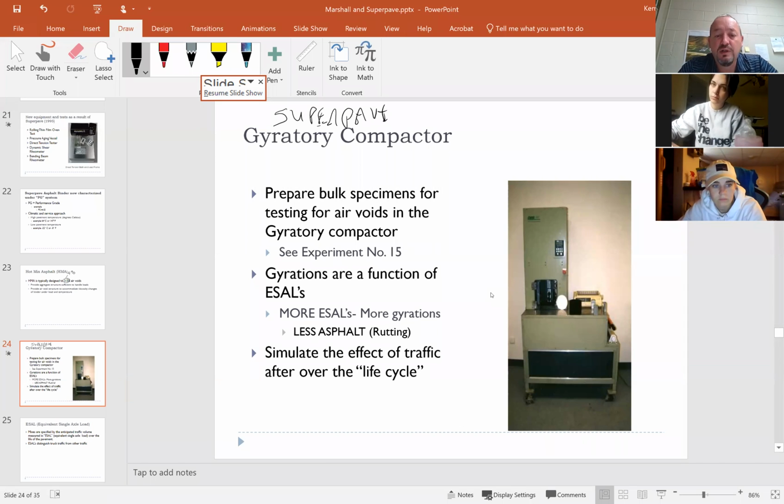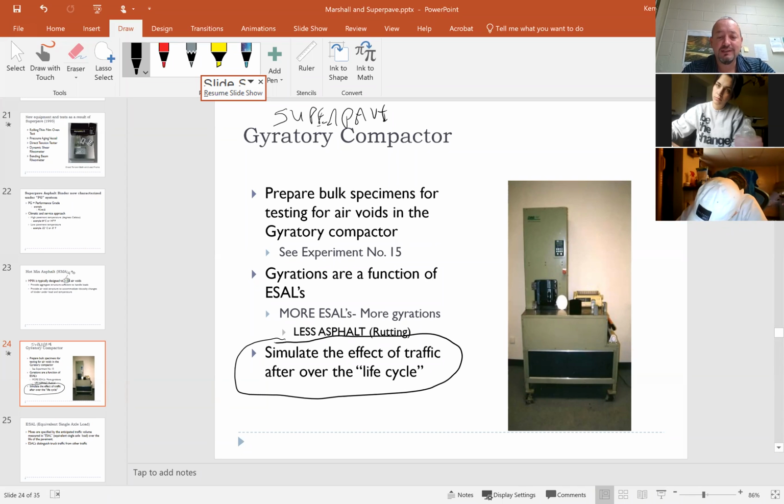Superpave gyratory compactor. So again, it's not really just, we compact straight down, and there's not a lot of sense in that, but actually it's more of, once again, a kneading or, they say, a gyratory type of motion. So the whole purpose behind Superpave was this thought right here: how can we more accurately represent what a pavement experiences in the real world?